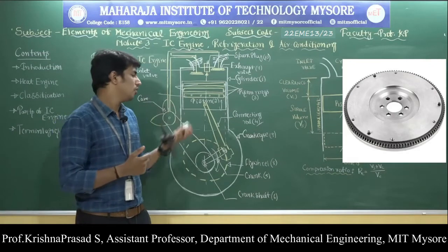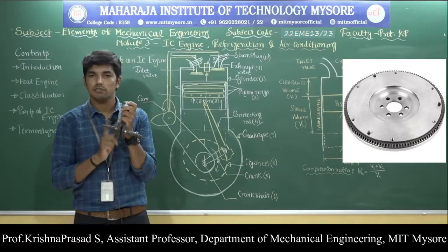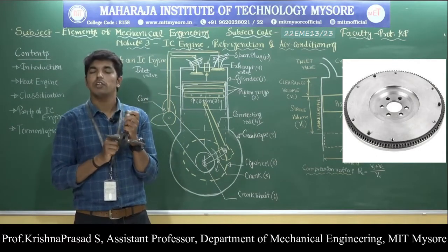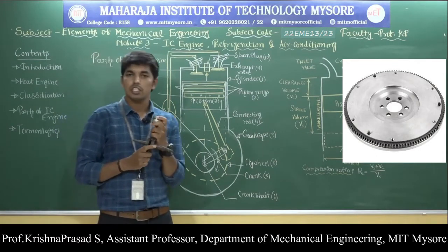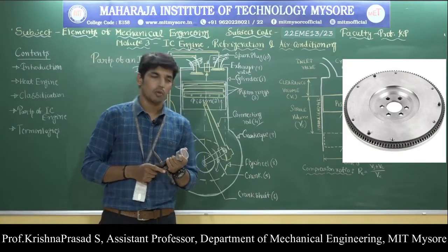So this is regarding the flywheel. Okay, so what is a flywheel? A flywheel is the heavy wheel mounted on the crankshaft of the engine. It absorbs the energy during the power stroke and supplies the same energy during the other three strokes: suction stroke, compression stroke and exhaust stroke.